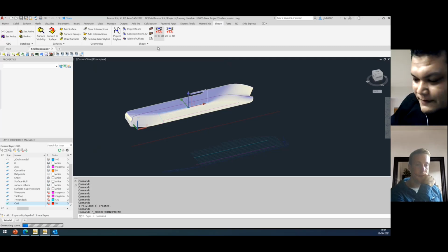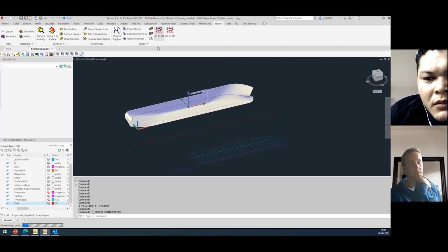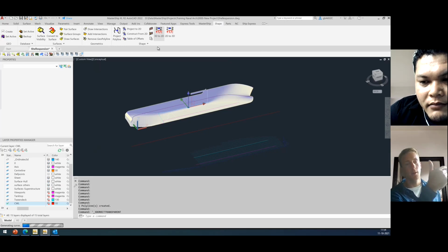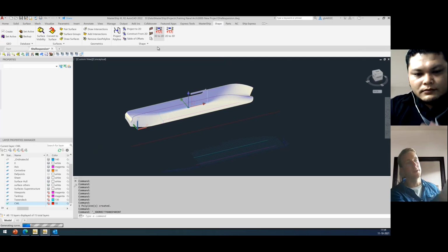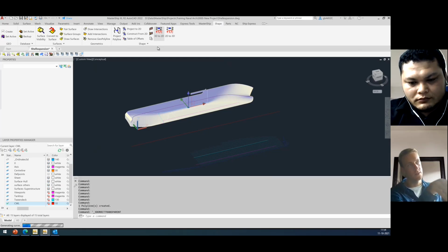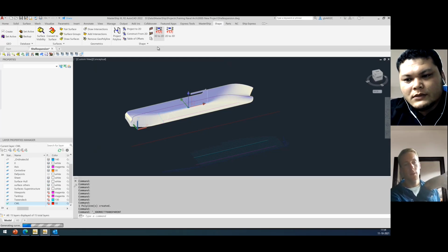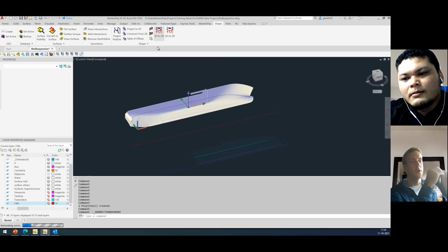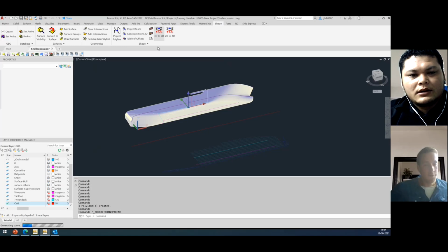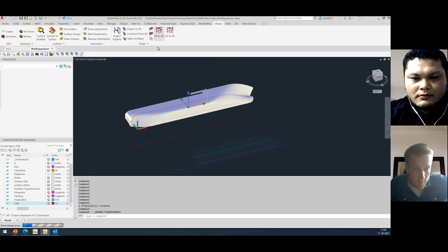That's also possible. You can also do a normal polyline. You can do line, polyline, 3D polyline, splines. Doesn't matter, but I made a 3D polyline now since that's the most accurate. And I wanted to join the two lines, and therefore I did that. I also could have used a normal polyline, which was also fine.